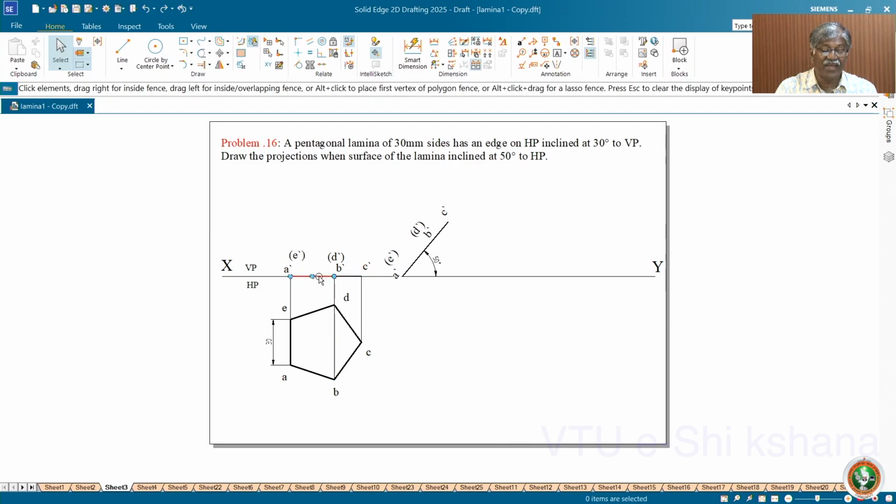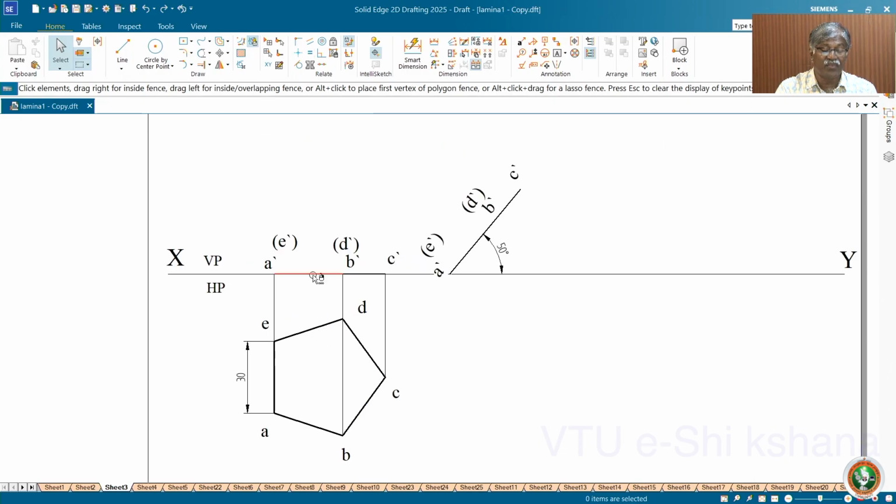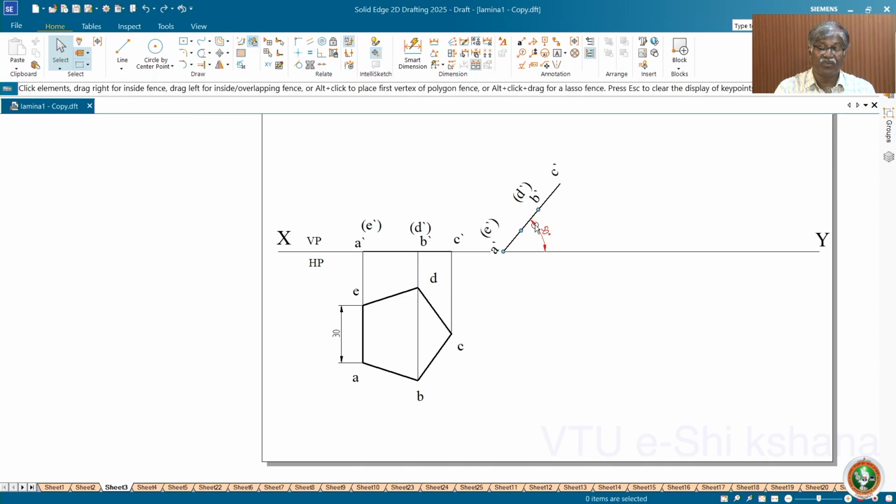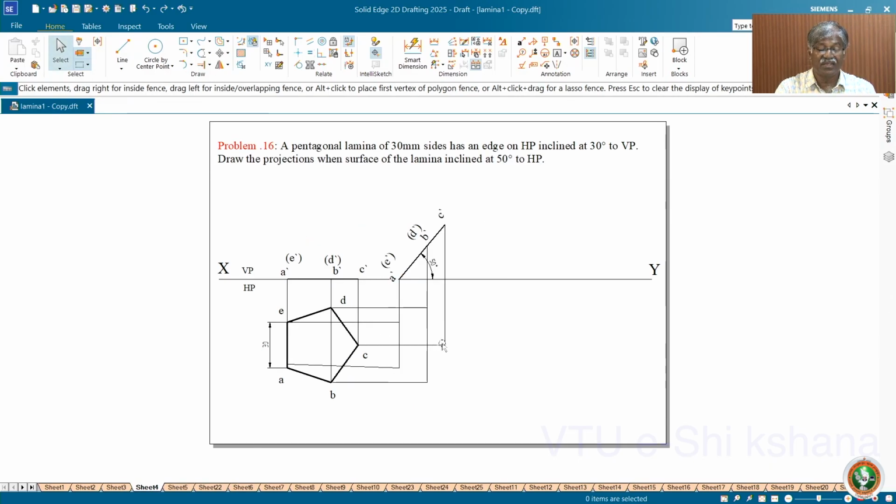another entity. I have done like that only. You can see the red mark here. Again you can see the red mark here. If I select this, I will select only this. Then this end point will come so that you can project as BC. So for convenience, you can take the line command and then draw a small thin line perpendicular to it and do it. Otherwise, you can measure this and then draw a line. Either way it works. But you should know how to locate these points. So I have located those points and then project it and get the points ready.